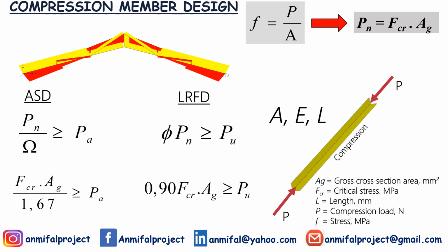I said that the nominal compression load should be reduced by a factor. For ASD, we divide the nominal compression load by 1.67 for allowable strength design. And for load resistance factor design, we multiply the nominal compression load by 0.9.